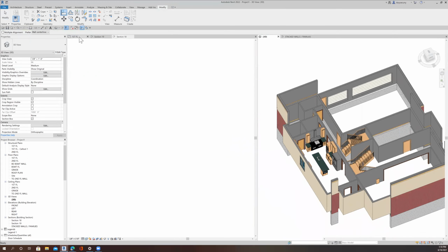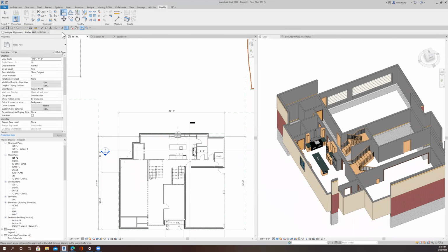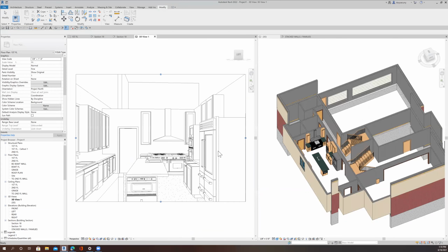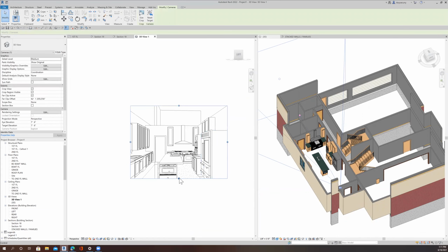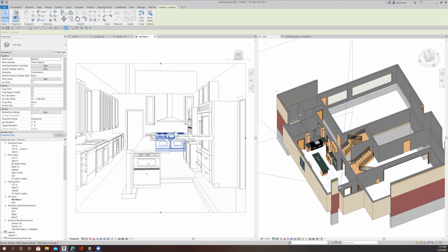All right, let's take a look at it. I didn't do anything down here underneath this island, but I want to take a camera shot of my kitchen. There's no floor in there yet, or there's no ceiling. That looks pretty good. So ZE for zoom extents. In AutoCAD, you type Z, enter, E, enter. But in Revit, you just type ZE.